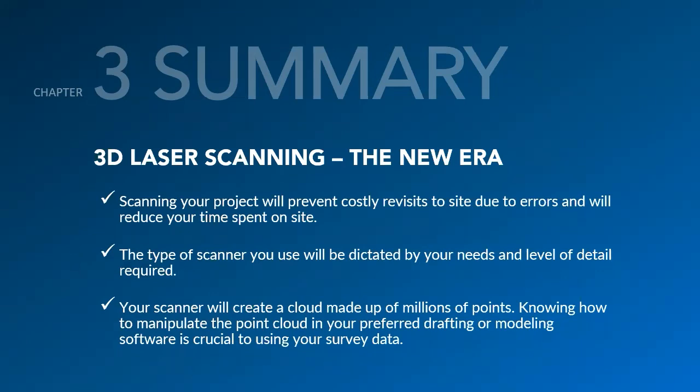data. And as an added note, while LiDAR has been around for about 20 years, more and more as-built surveys of all types are shifting away from the traditional methods to utilizing the latest in laser technology. As with every new production method, there is a learning curve, but once mastered, the entire process gets much smoother. And especially when incorporated with BIM technologies, the entire construction process can get a boost in speed, efficiency, and have a lesser environmental impact. That is it for chapter 3.